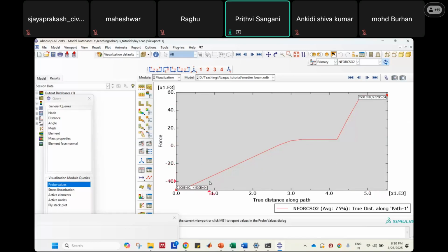And this is about the shear force diagram. So shear force is something like this. It goes down here and it goes linearly. No, it doesn't go linearly. It is kind of a parabolic function here because you have a UDL in this span, and then it is constant because there is no load in this span from 3 meters to 4 meters. And from 4 meters onwards you will have again a linear one because at 4 meters you have a vertical force acting, so you have something like this, and then after this you have a reaction force at this support.